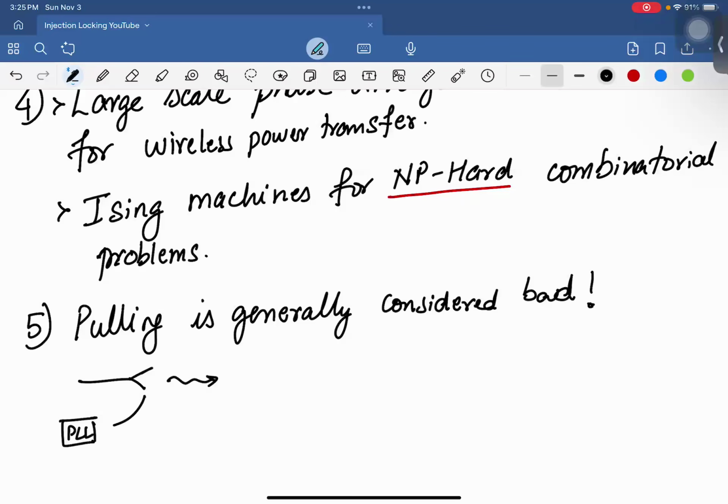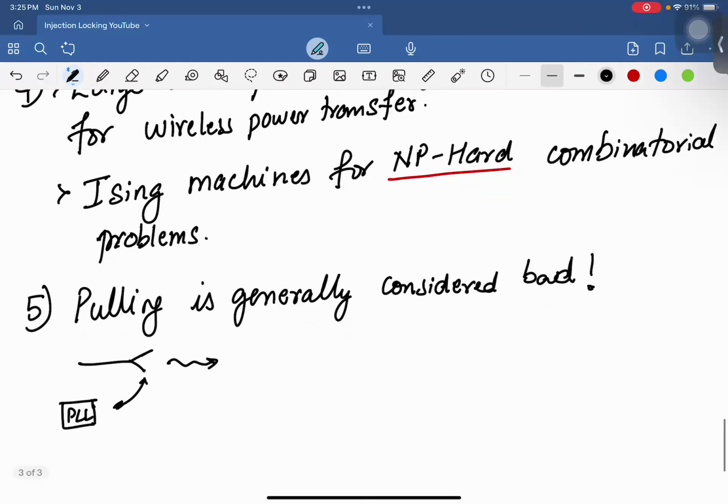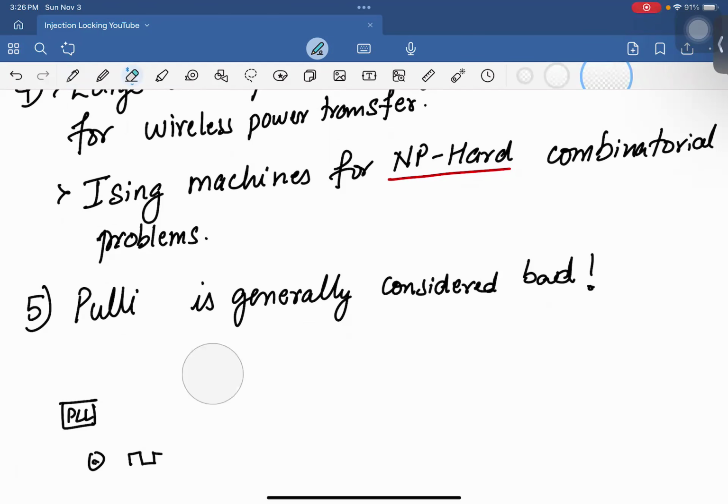And then there's some substrate coupling between these two. You can pull the PLL's signal with this high power transmitted signal, and you could have like two oscillators on the circuit or an oscillator and a clock signal that can pull each other and things like that. So understanding and quantifying, I guess, this phenomena of injection pulling as well will be very useful to us, especially when we do PLL design.